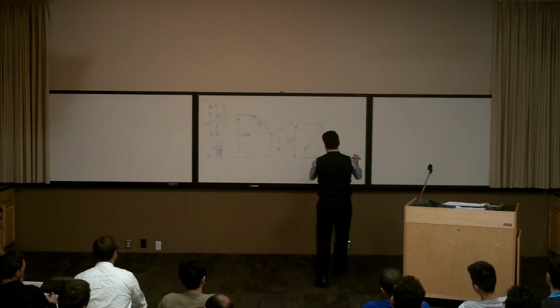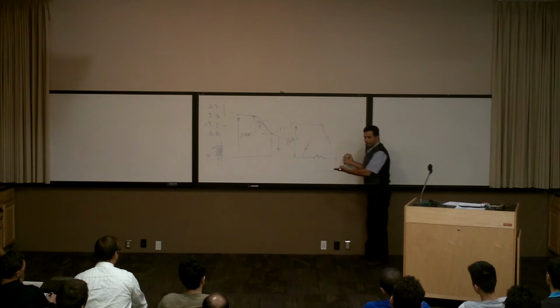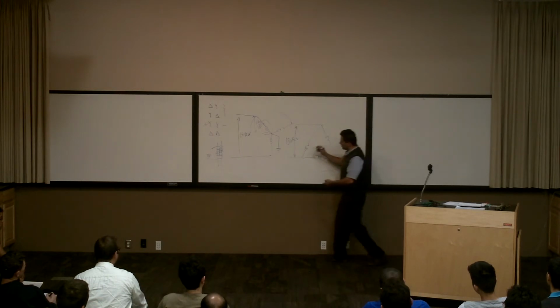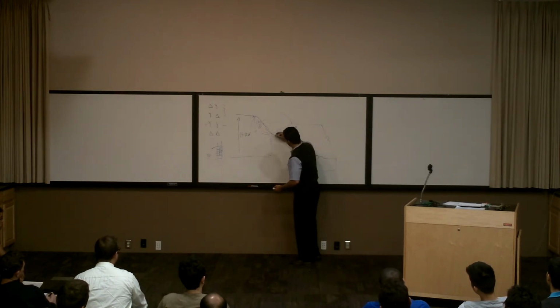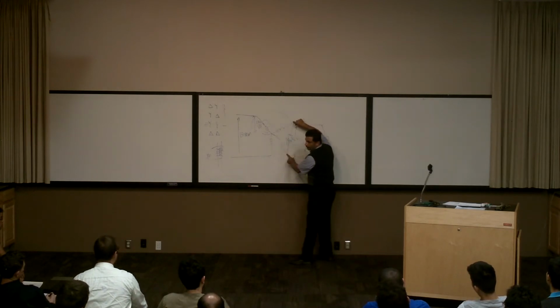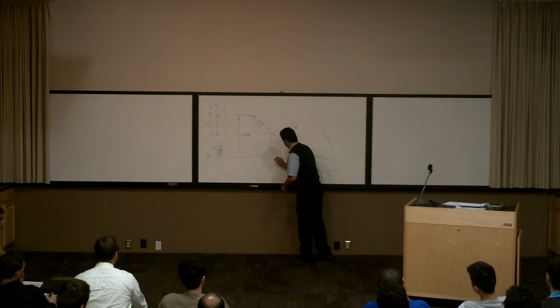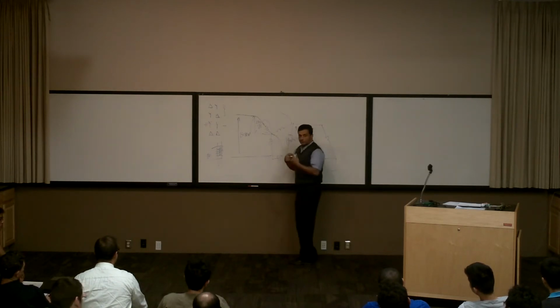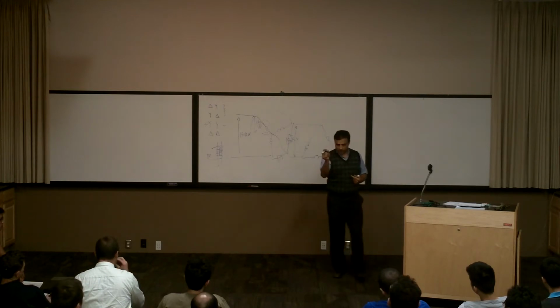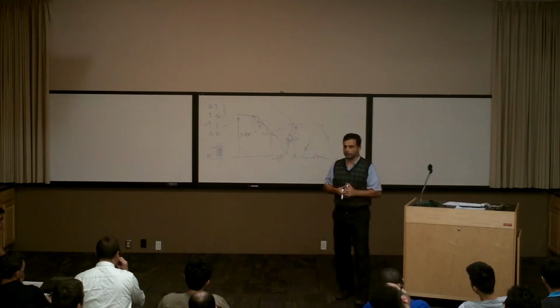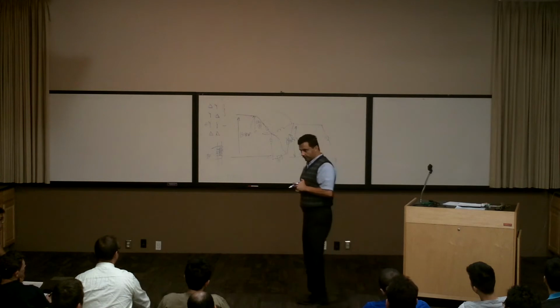Here, can I supply a single phase load? No, I don't have any neutral, right? But in this case, I can put one load here. For example, this is my neutral, right? I'm going to put one load here between phase and neutral, right? I can put another one here, for example, between phase and neutral here, right? So the Y connection, because of the neutral point, provides you the fourth wire. You can use it for single phase application.